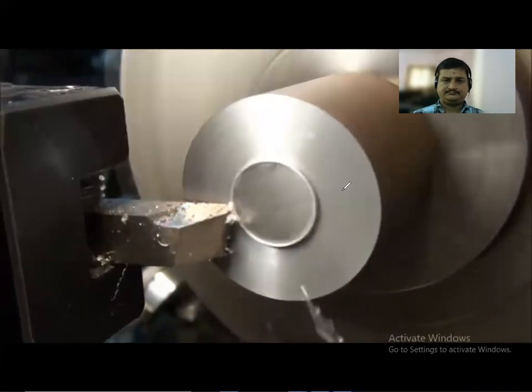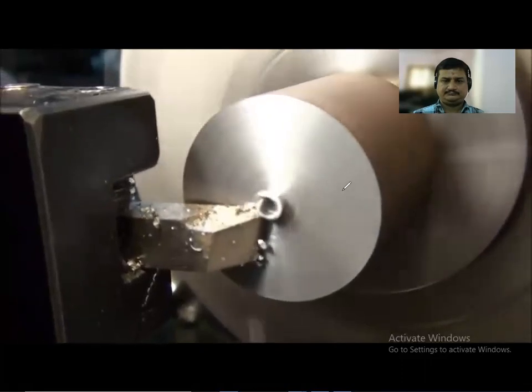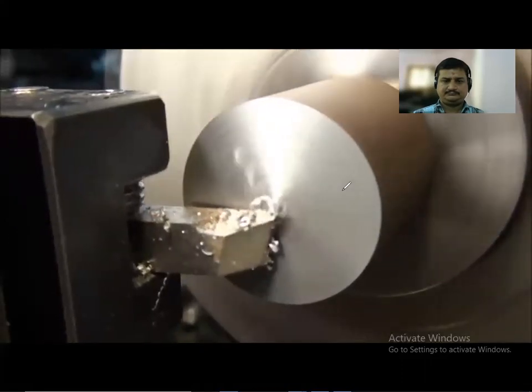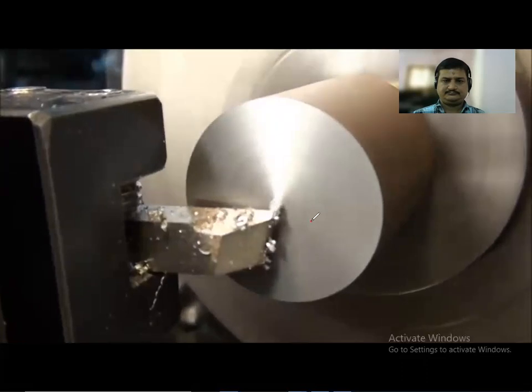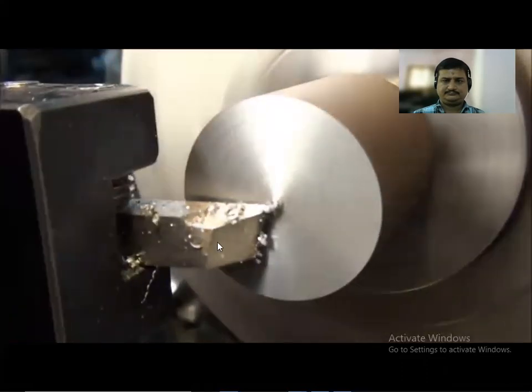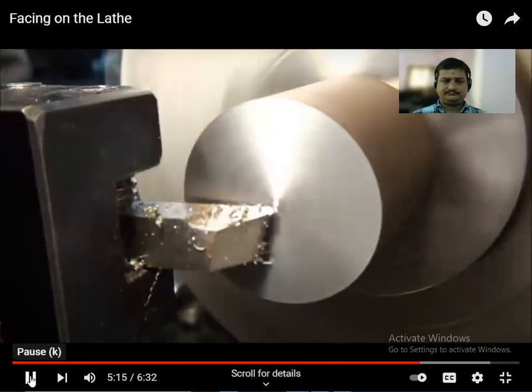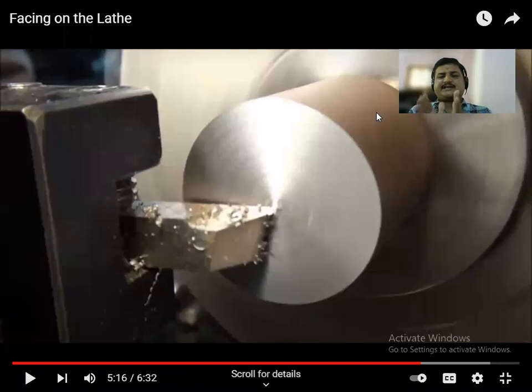Just clean out most of that saw cut. Okay, then we can tell how far we are off on center. It looks like we're a little bit low, so let's raise it up a little bit so we get rid of that little nib of steel left in the center there. A little more. Have you seen the first rough cut?